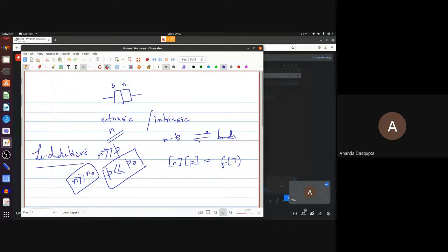So now what happens is this. Electrons and holes, when they're created by thermal excitation, are created in equal amounts, right? Each bond breaking creates one electron and one hole. Now, when the temperature rises a lot, and because bond breaking increases exponentially fast with temperature, a stage comes when the electrons and holes essentially become almost equal.